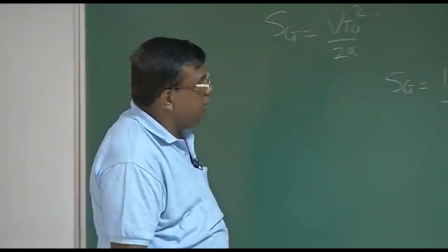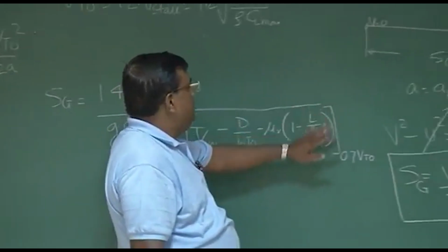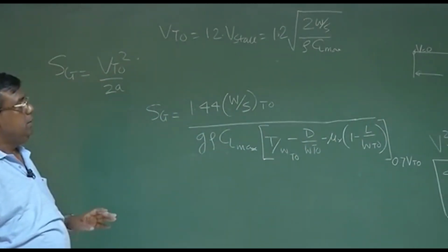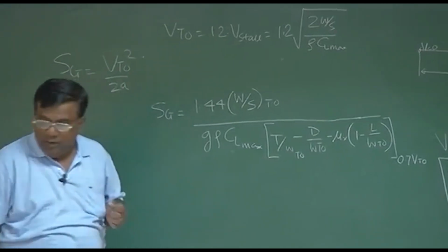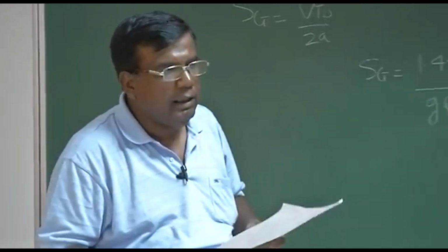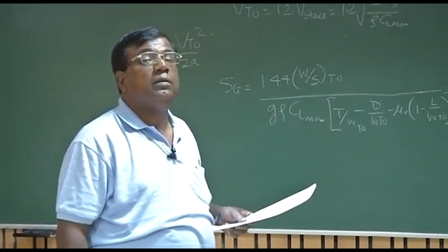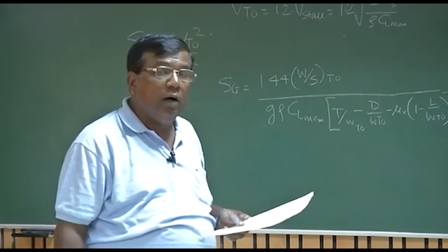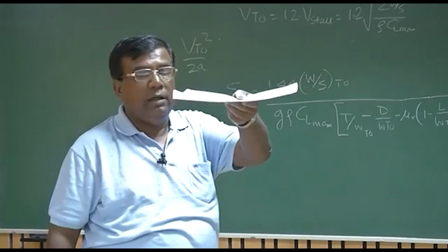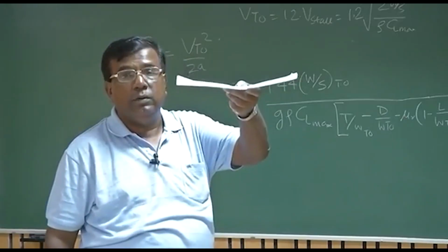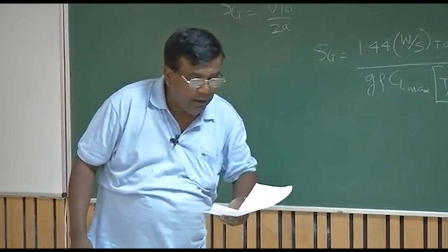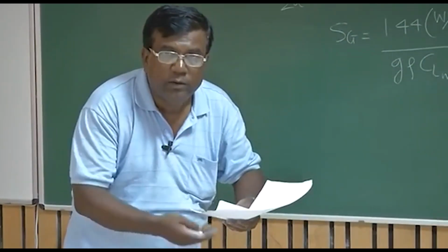Okay? As I was mentioning, do you think the whole effort for calculating SG is over here? Let us see or visualize one thing. So far, whatever aerodynamic characterization we have done, that is estimation of CL, estimation of drag polar, understanding about downwash, all those things were when the aircraft was flying in air, far away from the ground. Now imagine when this airplane is taking off from the ground, so these wings are very close to the ground.